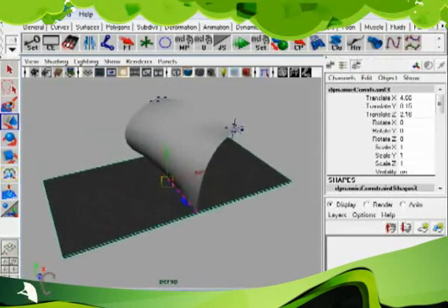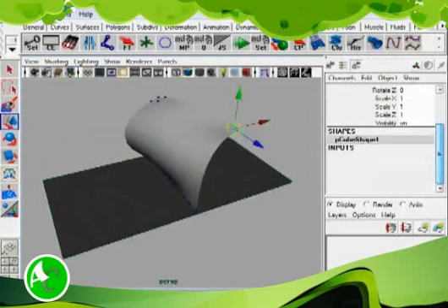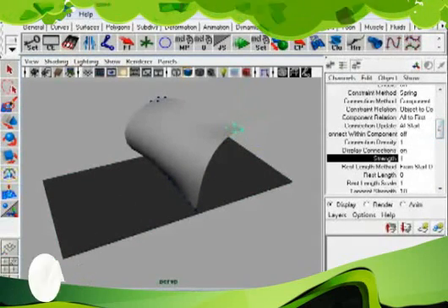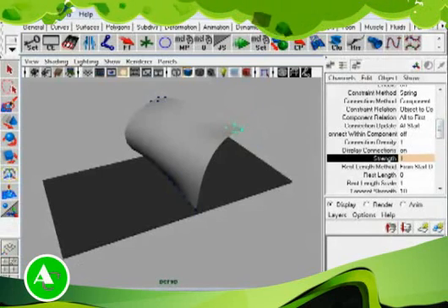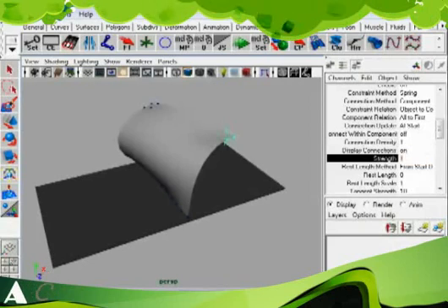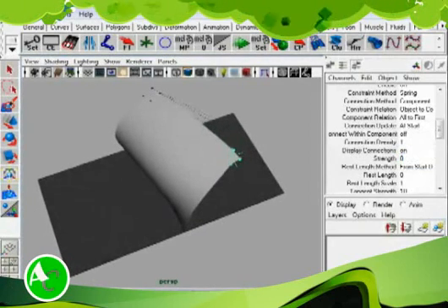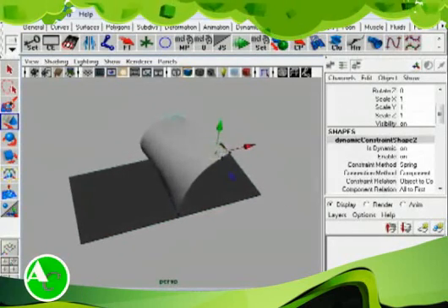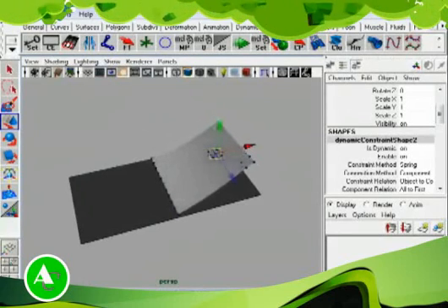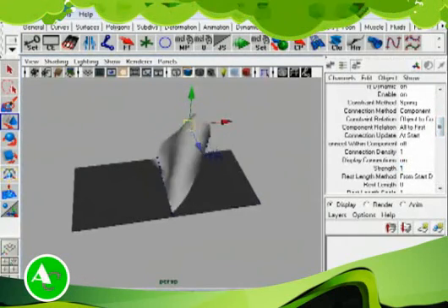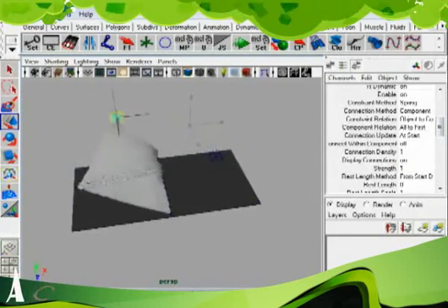While animating, the animators can just animate on the transform nodes and the dynamic constraint's strength value. They can just key on it, set how much strength they want, and work on it. What I mean is, if I set this strength to 0, and this time I select the dynamic constraint on the other side and try to move it, this dynamic constraint no longer has any influence on it. If I set the value to 1, it already pops up, and you can just turn the page like that.